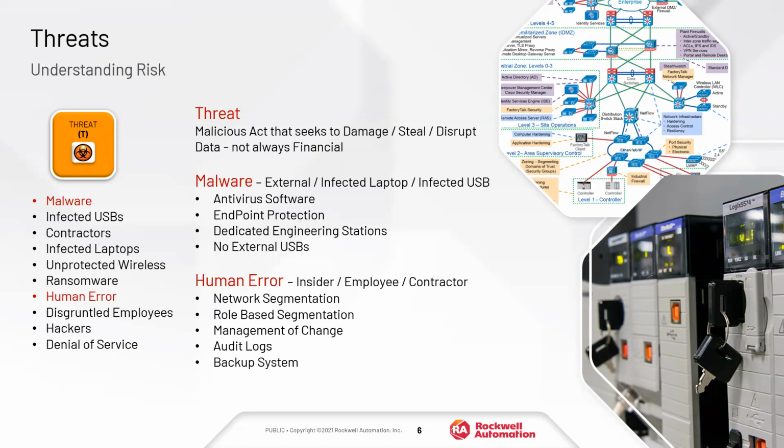We'll talk about some of the countermeasures there. Also, potentially changing the wrong set point. You're on the wrong graphic screen on your SCADA system, on your panel view, and you go in and change the set point, then realize that that set point change was on the wrong page, on the wrong system, the wrong area.